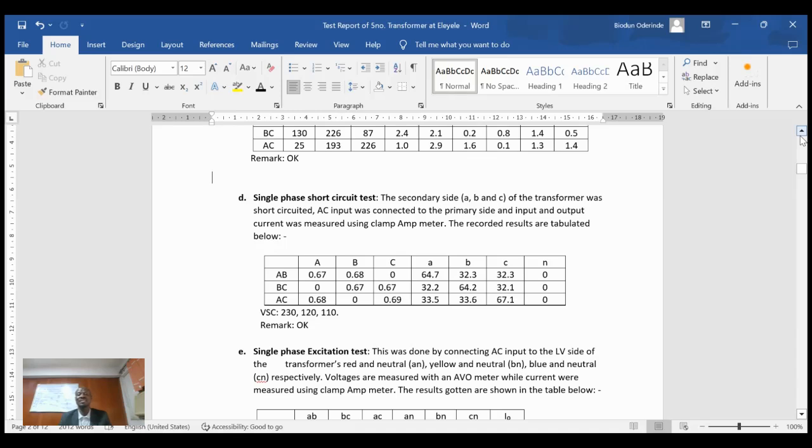We have instances like this, where we have it on the nameplate of the transformer to be a particular capacity, but if you do the short circuit test, it may not be. So that's why it's very important, especially when we are doing pre-commissioning tests, to do the short circuit test or capacity test to really know the capacity of that transformer, because if they told us that transformer is 300 kVA, for example, we need to have it in our database.